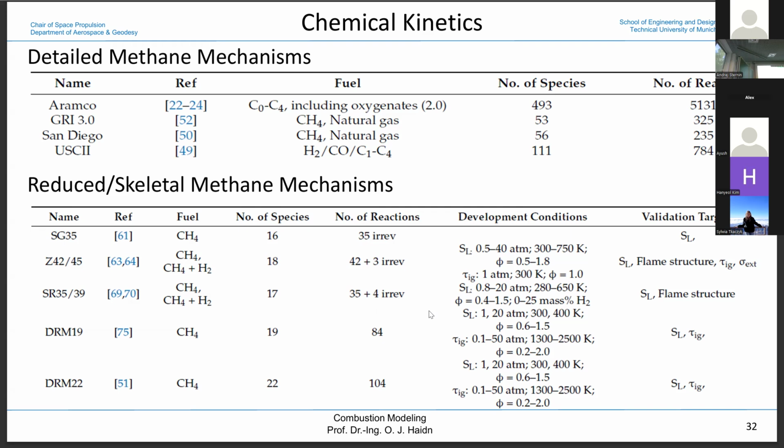Say this is a rapid compression engine. I assume this can't be really good because if you move the piston, you also initiate some kind of flow. The flow may impact the flame propagation and the mixing locally. So this is an early experiment, but it has a larger error than a well-defined shock-tube experiment or some plug flow reactor. So we do some kind of uncertainty assessment of the experiment. We say maybe we don't believe the data point 100%, but maybe 70-80%. If we do this kind of optimization with uncertainty quantification, our mechanism is doing better.